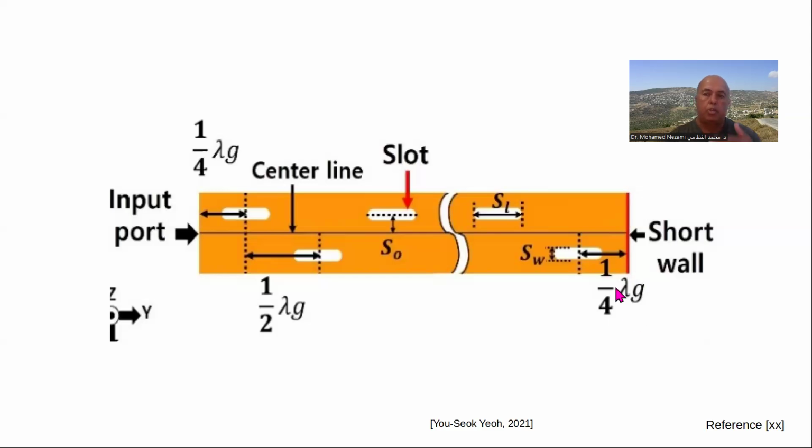Or in my case, I use 3 quarter wavelengths. You can do whatever odd number of quarter wavelengths in here. It will all work, okay? And then likewise, at the beginning, from the input, the illumination input, to the center of the first one is also another quarter wavelength.